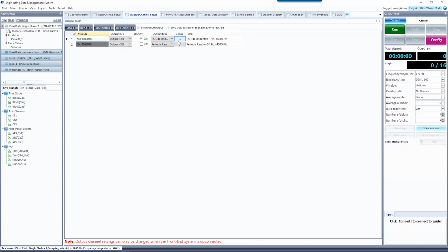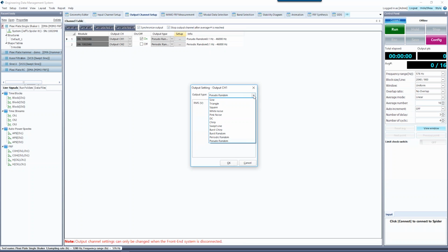Typically, we all know with the hammer impact test, the test setup is quick and easy, and it doesn't require a modal shaker. The setup is much faster. But for many structures, people say, let's use a modal shaker. With a large channel count dynamic signal analyzer and multiple transducers, it's more efficient to finish the whole test, because you can have a 32-channel analyzer with 31 accelerometers and 1 force sensor, so you can get 31 transfer functions in one shot.